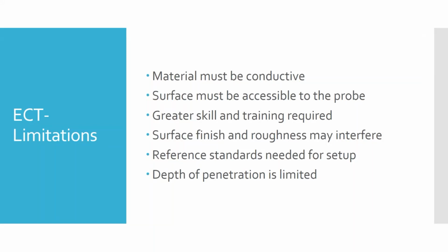So similar geometry, similar surface finish, and the same material, even down to the alloy level. So we do have these reference standards needed for setup. So it's got specific purposes you're going to use it for, rather than just a general crack inspection of something like a crankshaft.